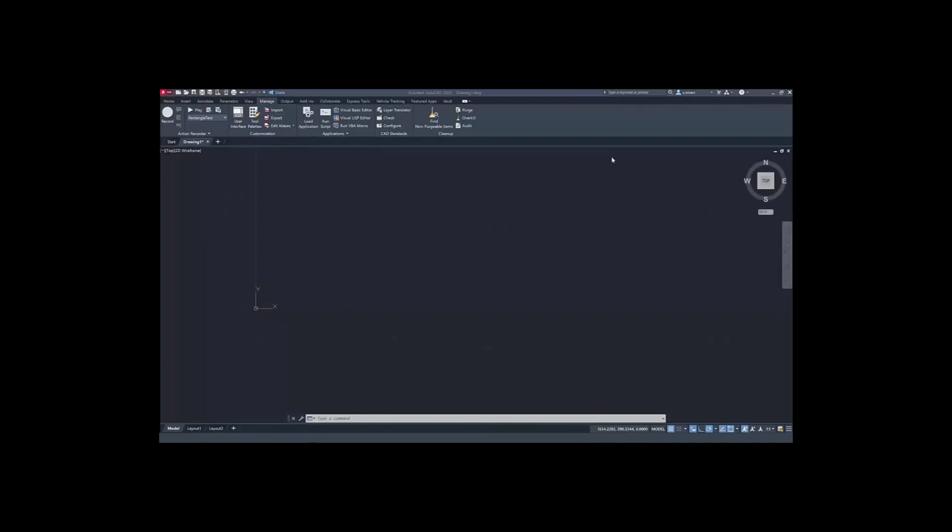The last little thing I want to show is just how we can load lists directly into AutoCAD. So if we wanted to load a list directly, not using Visual Studio Code, so say we have a list that we've created, we know it's working because we've done all of our testing, and we want that to load every single time we open up AutoCAD. What we'll do is here under the Manage tab, under the Applications tool palette, we have this Load Application option here.